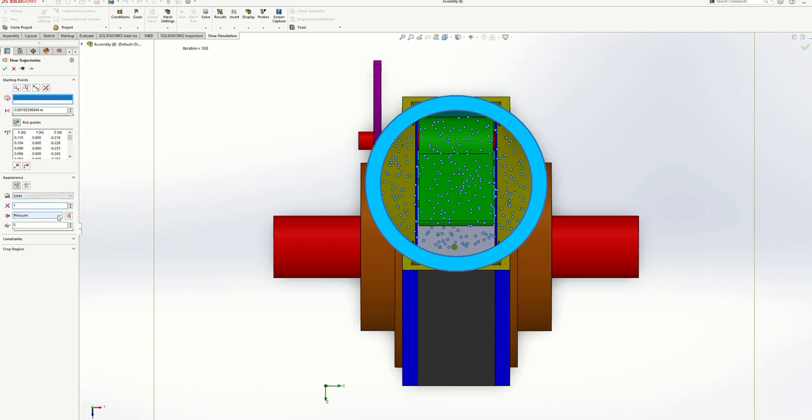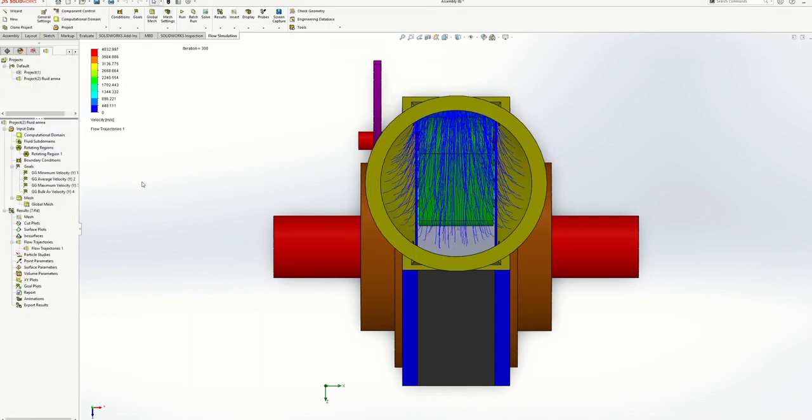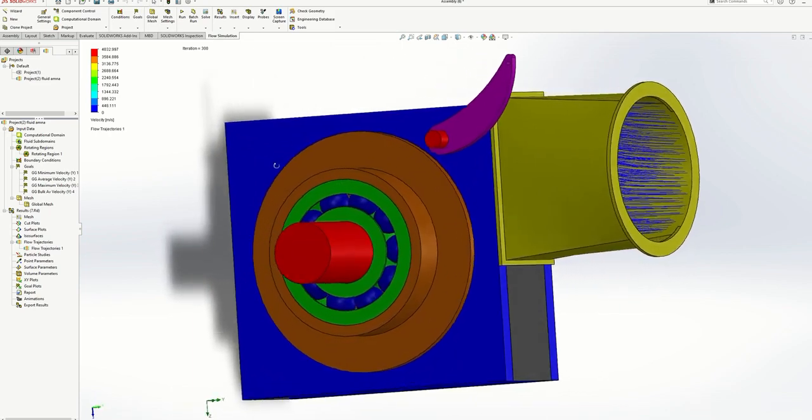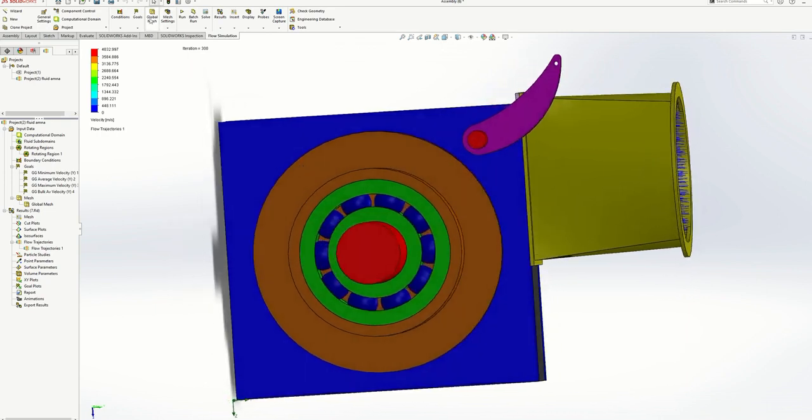And I'll select velocity. You can switch between all these anytime you would. I'll show you later. I'll hit OK. Okay, as we can assume that the highest velocity is 100 meters per second. So let's assume that the highest velocity would be 110 meters per second. So I'll double click in here and insert 110, then OK.